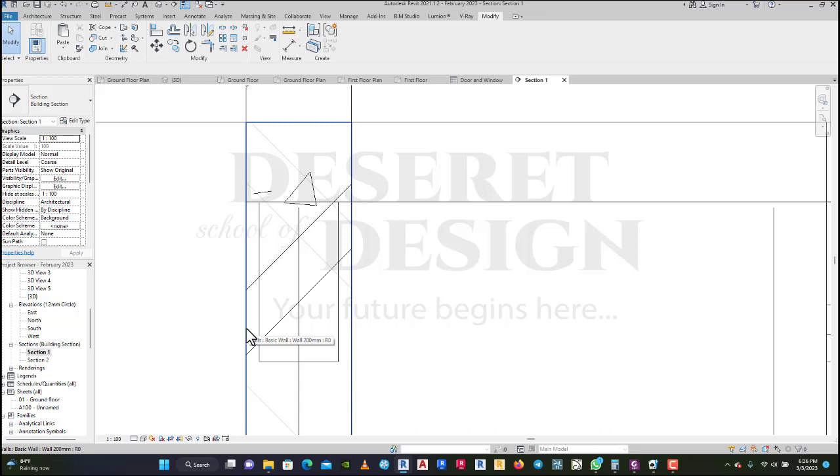Do you get it? So we have a tool called a joint tool that you can use to separate them. Like join the two, but then the hatch patterns will not go through each other. So you click on your joint tool. Now look at the procedure in which I'm joining. First, select your beam and your wall. Now you can see that the wall pattern is no more going through. Then the next one you do is select your floor and your beam. So now the floor and the beam have been connected.